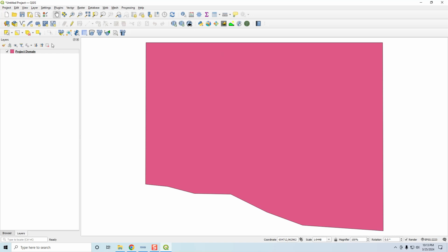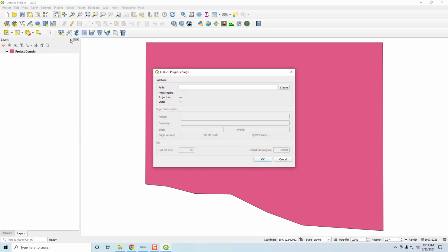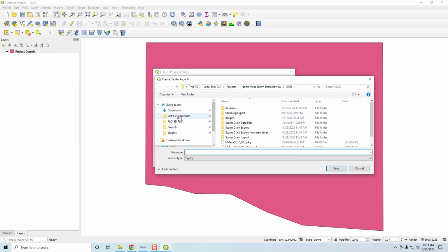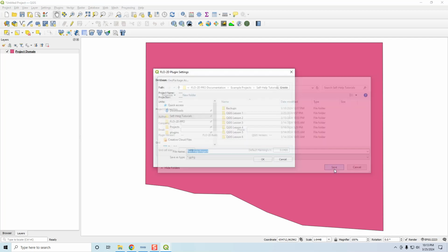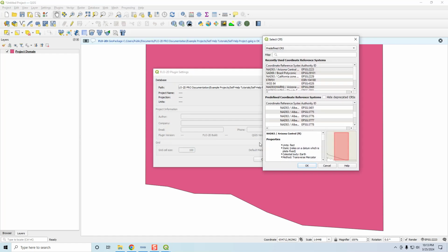The final step of this video will be to set up the project. So we are going to click Flow2D Project, New Project, and we're going to create a geopackage in our self-help tutorials, and we want to put it right here. Let's just call it self-help, or self-help project, whatever you want to call it. Click Save, and now it is going to be building the geopackage.